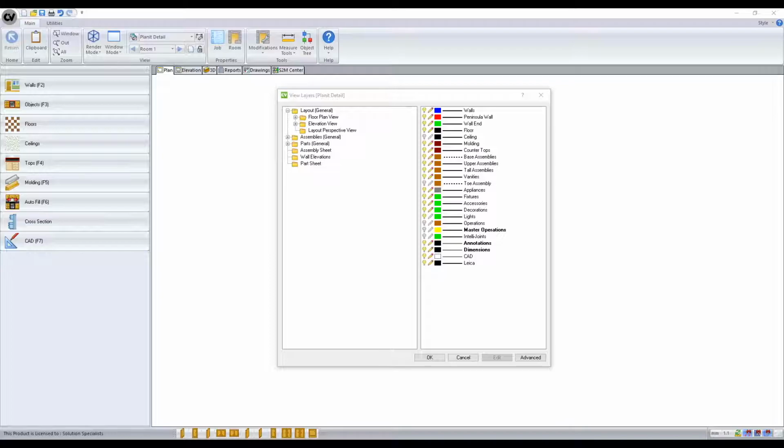Layers. What are they? Layers are used to control what you see in different views in Solid. Layers are overlays on which you organize and group different drawing information. Solid Essential and Standard customers have just a one layer schedule on which they can edit. Advanced and Ultimate users have the ability to set up multiple layer schedules. Layers do not control what is actually in the job. They only control what you can see on the screen and which details are sent through to the drawing scenes.